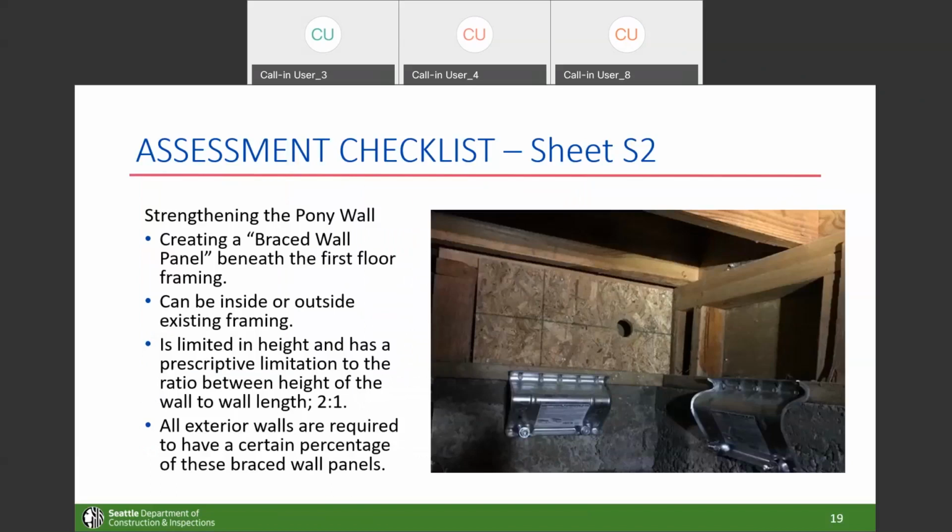All right, so creating the braced wall, even if it's pretty short, the oriented strand board there is a good example of one of the panels that they'll put in. And then underneath it, those silver, interestingly shaped anchors, that is what's known as a flexible side anchor. That's a case where they actually come in from the side and connect the wood sill plate to the concrete foundation below.